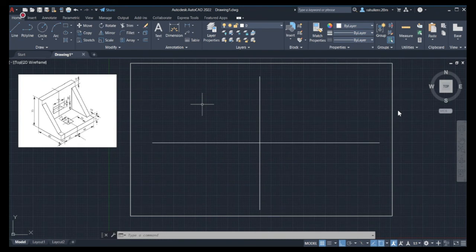Yes, sir. Okay. What I am saying here is, right now, looking at the object, we are going to see the left side view of the object. When we see the left side view of the object, the projection is going to be on the right profile plane, which will be on the right side of the front view. So if you somehow draw the front view here where the cursor is, then you cannot draw something to the right of that.